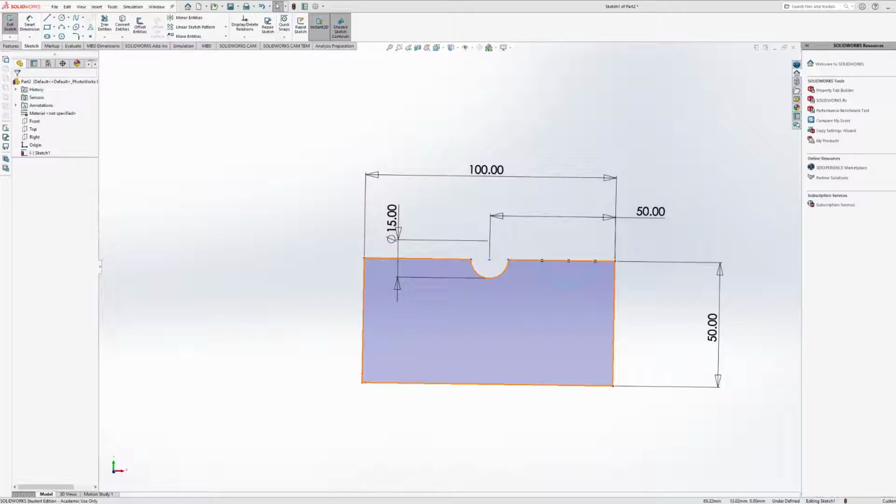If you want the dimensions to be on the drawing, you don't necessarily have to smart dimension things. Creating dimensions on the drawing is a lot easier, admittedly, just because it doesn't come with as many restrictions.